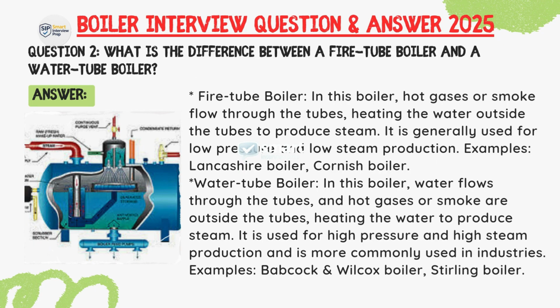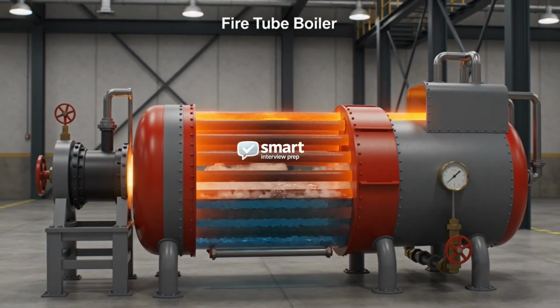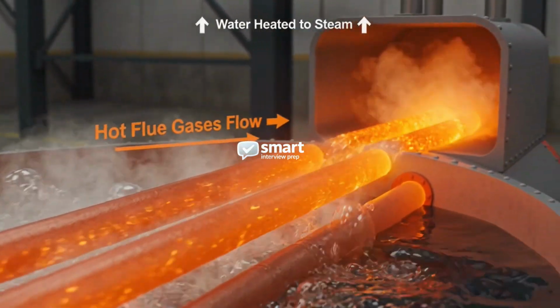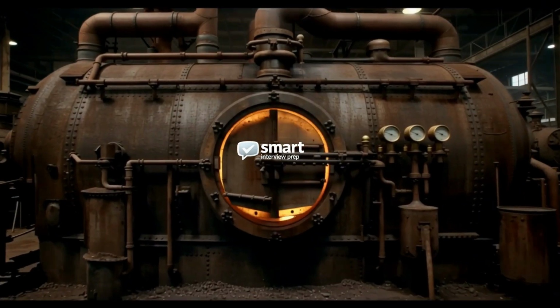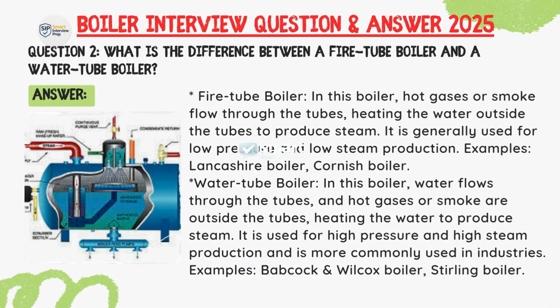Question: what is the difference between a fire tube boiler and a water tube boiler? Answer: fire tube boiler. In this boiler, hot gases or smoke flow through the tube, heating the water outside the tube to produce steam. It is generally used for low pressure and low steam production. Example: Lancashire boiler, Cornish boiler.